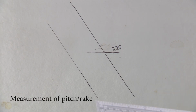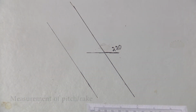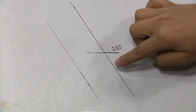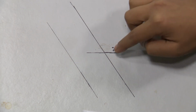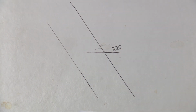Now we will measure the pitch of these lineations. Consider this line on the whiteboard as a linear element in the deformed rock. The pitch is basically the acute angle of the lineation with the strike line, in the plane containing the lineation itself. So this is our acute angle.